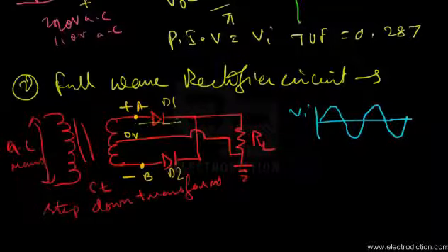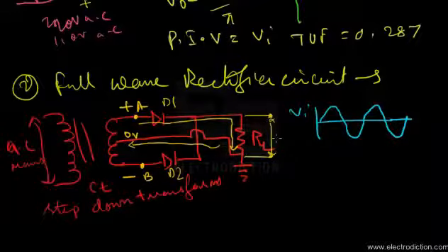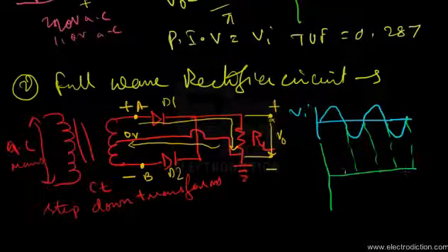So there will be a current flow through the load resistance and then back to the center tap terminal, and due to this current flow through the load resistance, there will be an output voltage generated with a polarity as shown in this diagram. So based on that, if we just draw the characteristics of the output, then we can see something like this. Okay, there go the half cycle divisions.